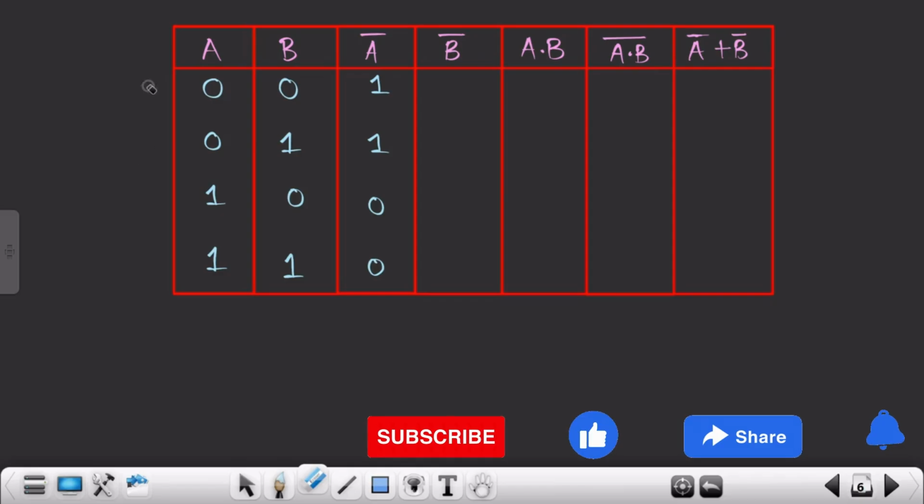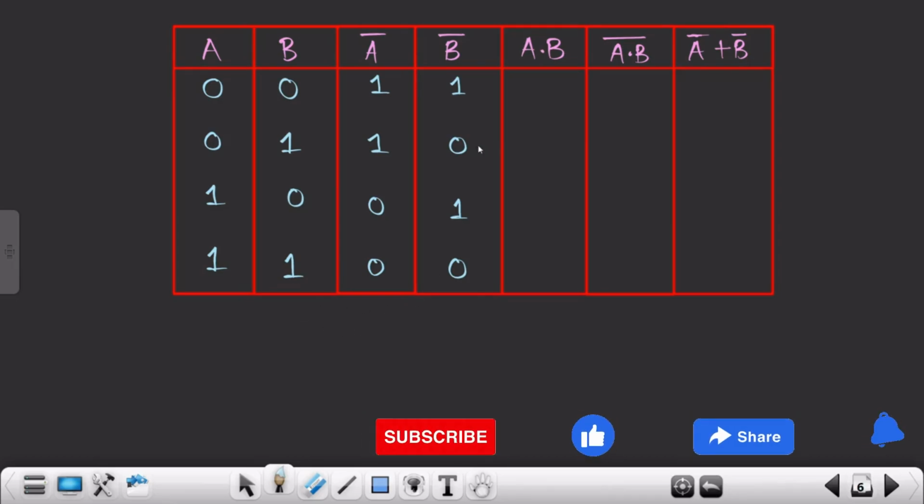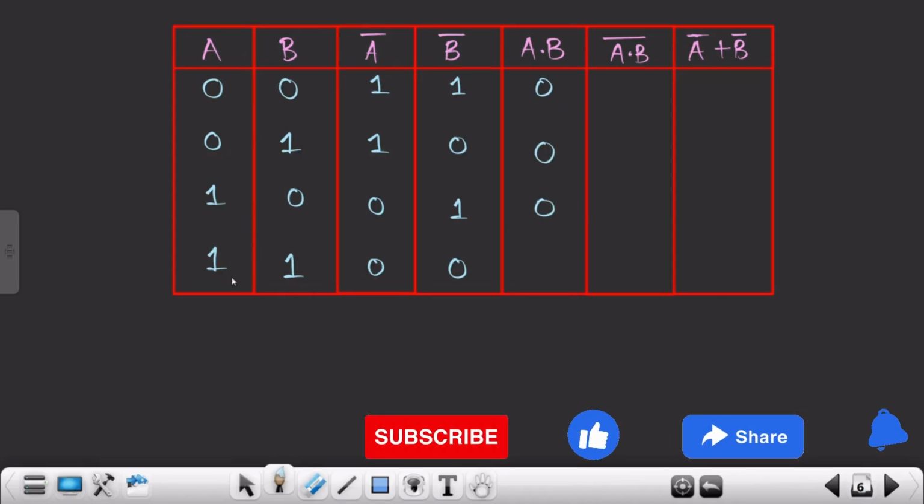Now the same goes with B as well. B is 0 1 0 1, so B bar would be 1 0 1 0, right? Just the inversion of B. Then we just need to multiply these two logics, the inputs that we are feeding, that is A into B. Obviously this can be done with the help of an AND gate, which we saw in the previous sessions as well. So 0 into 0 is anyhow 0, and anything multiplied with 0 is 0. Great. And 1 into 1 is 1.